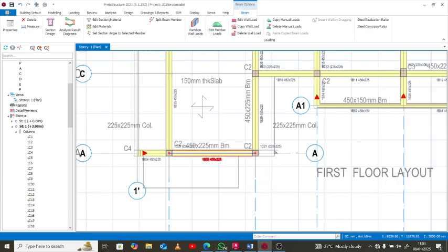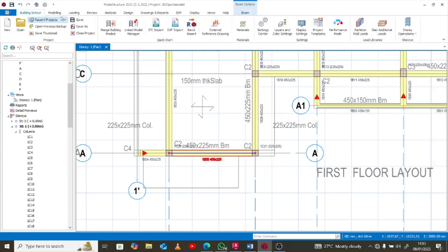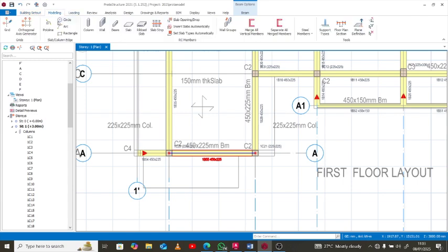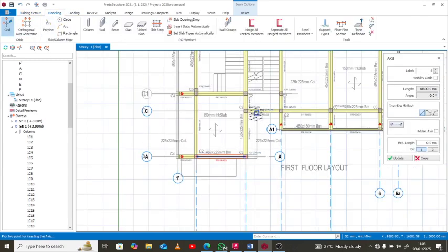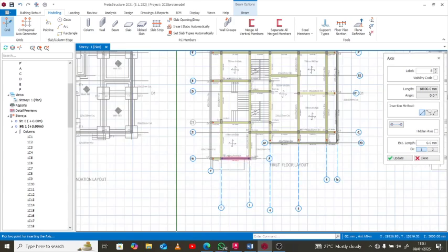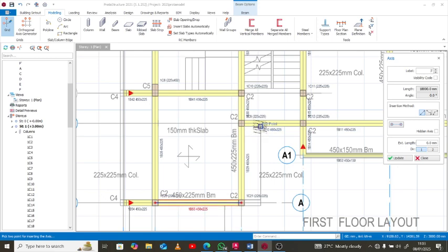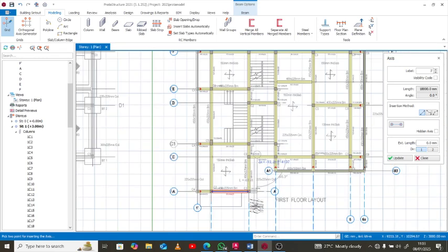If you want to make it get to that place, it's as simple as forming a boundary using a grid line at that point. So you may want to create an arbitrary grid line for yourself around the place. What can we call it? Let's call it 3 prime, just to form the boundary at which you want your beam to stop.